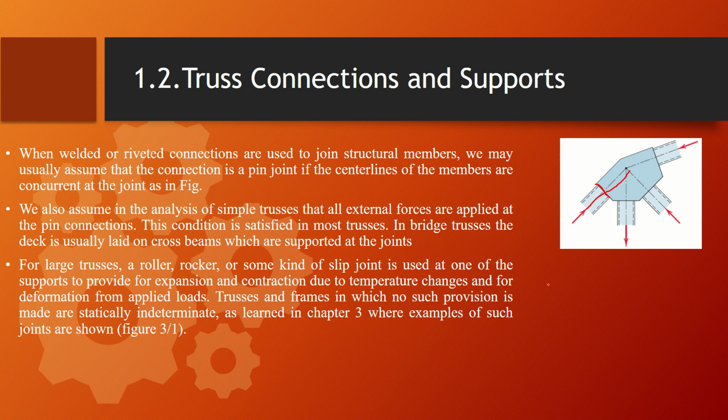There are two methods by which we can solve these trusses, explained later on. But you have to understand, the external reactions are determined first for any structure, by applying the equilibrium equations as a whole. The force analysis of the remainder of the truss is performed afterwards. The first thing you have to understand is that we have to develop a very good free body diagram for external loads, and then we are going to carry on to the internal loads. The first method